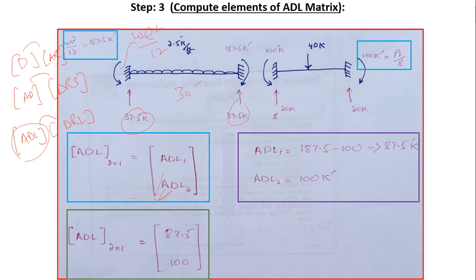So you insert 2.5 here, the length is 30, and you divide it by 12, and you will get this fixed end moment to be 187.5 kip foot. I'm not interested here. I am interested here because these moments correspond to D1. Okay, for this span, 40-40, that is 20-20, and that can easily be converted into